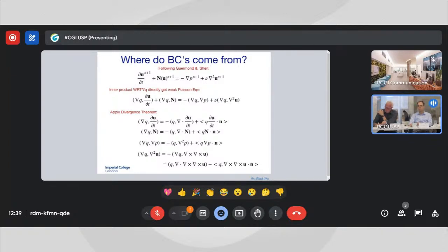This is what I'm doing all the way down. We've got our nonlinear terms. It's going to give me something that's on the boundary. Remember, we're trying to get pressure boundary conditions. They had these nonlinear terms evaluated in our boundary conditions on the boundary. We've got a term here for this third term, when we construct it, which gets us back to something that looks like the Laplace equation now. Here's my pressure Poisson system reappearing through the divergence term, and then I've got a condition that looks like the dPdn term.